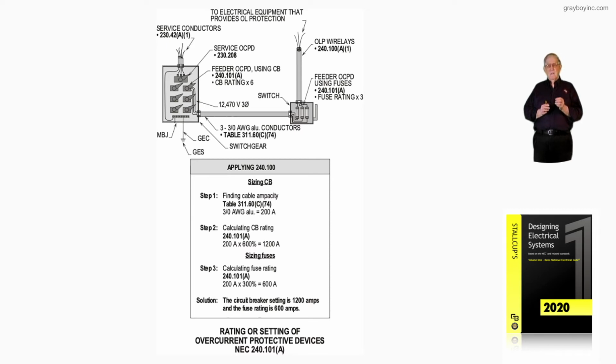And then notice that we're just dealing with conductor sizing here and setting of the overcurrent device. But for each individual component that you see in that illustration, that's not conductors and conduits, we would reference Article 490 to pull out our requirements for certain components over 1,000 volts. So with that information, let's move to step 1 in the boxed in information.